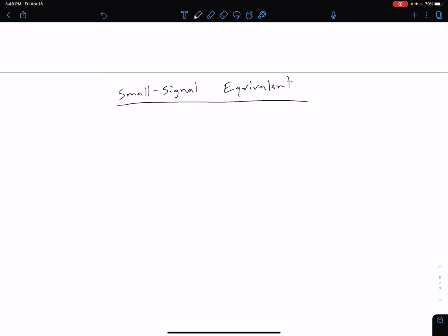So how do we characterize that transistor? Well, let's list a few of the things we know about our ideal transistor. For a MOSFET, ideally we have 0 current into our gate terminal. In practice, we know we'll have some really small amount of leakage current, but let's ignore that for the moment and say ideally we just have 0. As we saw in the previous video, our small signal drain current, or our AC drain current, is just equal to our transconductance times our VGS.